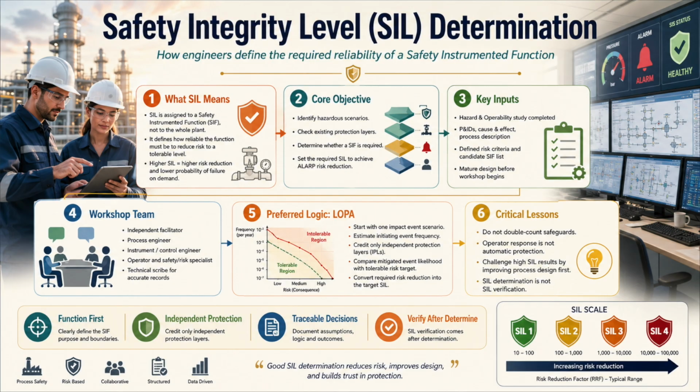The report is not simply a workshop record. It becomes a design input. Its results feed the safety requirements specification. That specification must convert the integrity decision into implementable requirements: functional logic, trip settings, response time, voting architecture, failure action, reset philosophy, bypass controls, diagnostic requirements, environmental conditions, proof test interval, test coverage, maintenance constraints, and interfaces with other systems.